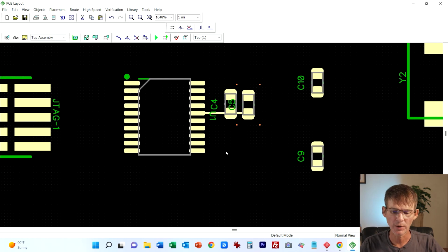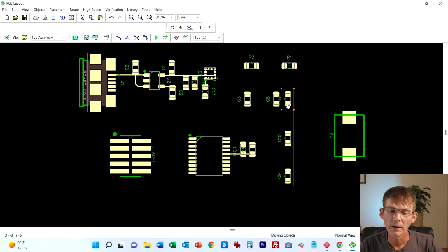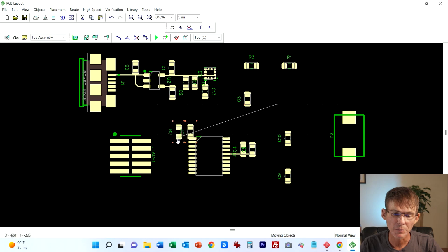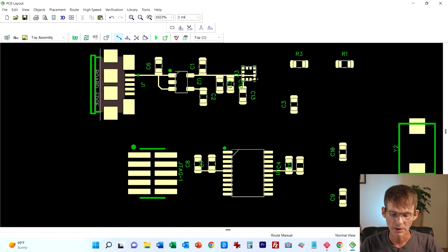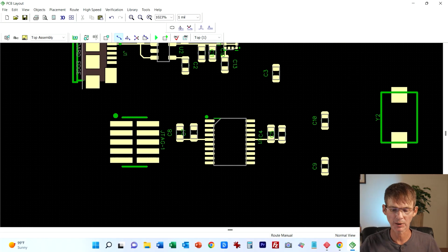We have those two, and now we need the 2 input capacitors for the VDDA, and those are 7 and 8. And we'll do the same over here. We'll just put those right here. Zoom in and connect those up. Okay, so now we have our input capacitor, we have our input supply done for the microcontroller.